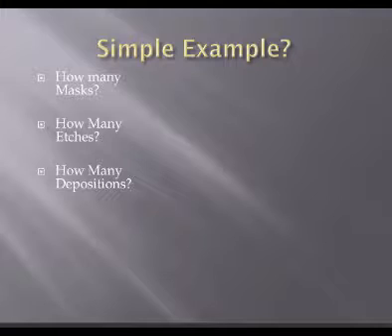So how many depositions? Well, material depositions, how many did we have of the ones that we care about? Yeah, the structural and the sacrificial, right? But some people might say, well, you're depositing photoresist, so that's a type of deposition. So I wouldn't argue the point, but as long as you understand you got 2 mask layers, but there's a lot of other stuff going on. There's several etches, several depositions involved just to make those 2 layers. Okay?